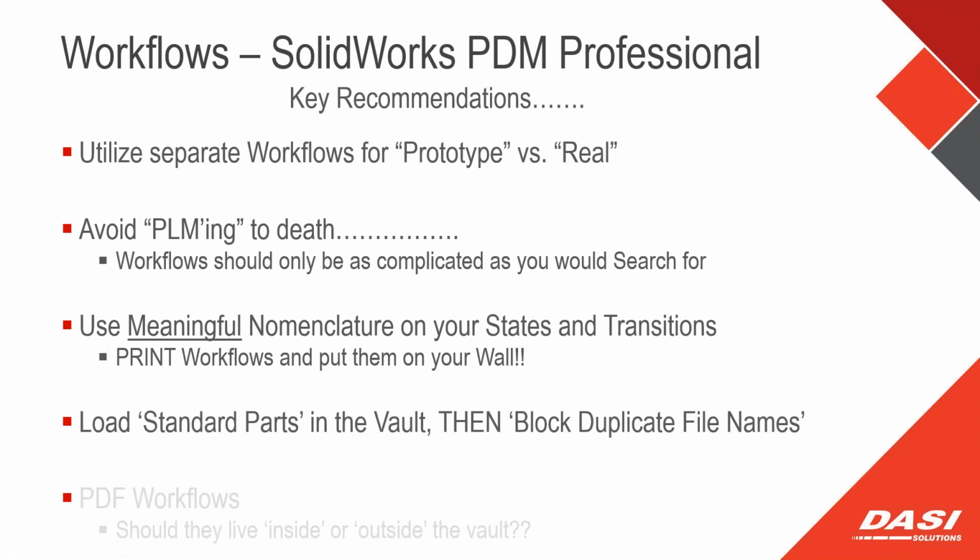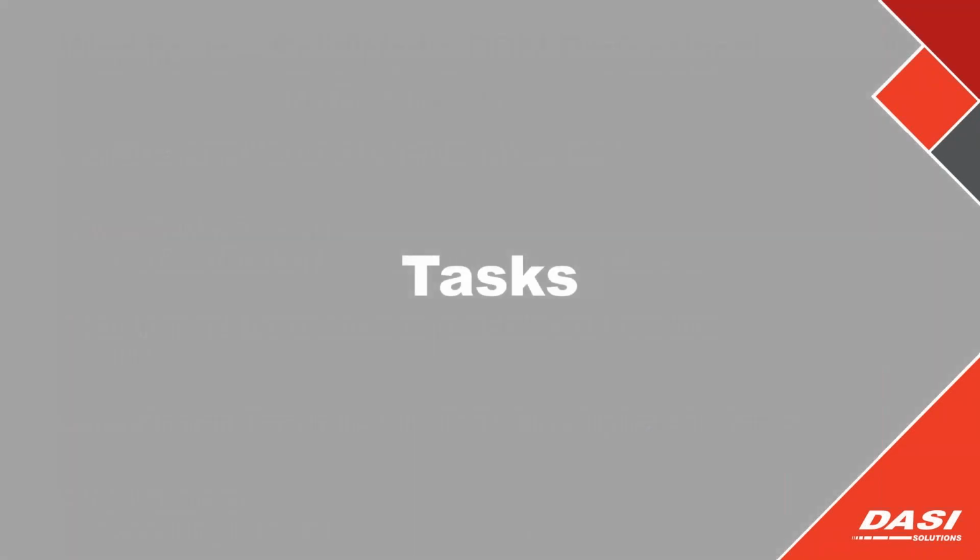Loading the standard components in the vault: clean things up, get them in there, and then load up all the folders with the actual designs, and it'll reveal a lot of those accidental copies that you've made just through using Windows the way Windows works. And last again was the PDF workflows. Inside or outside the vault, it's all about licenses here. I prefer them inside, but that's a cost. So we want to keep things as simple and streamlined as possible, keep them moving forward, throw them out where those individuals that use those PDFs always use them, and you can just decide later if you need to get them into PDM.